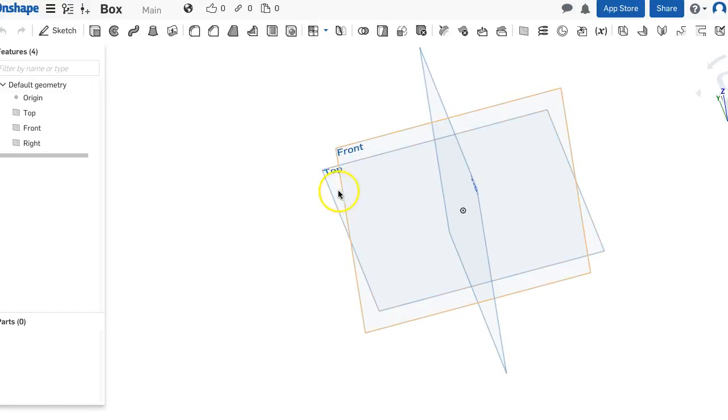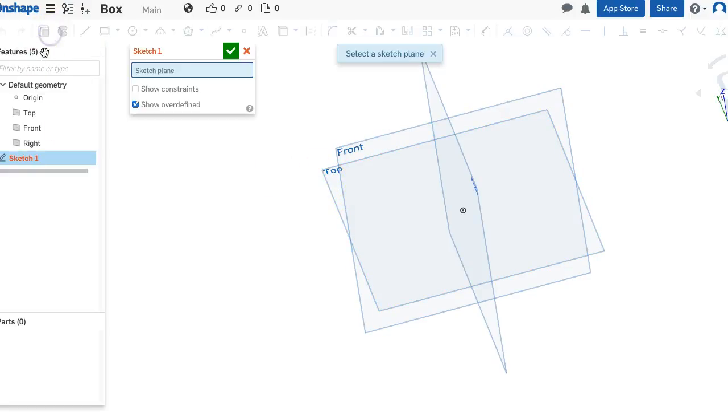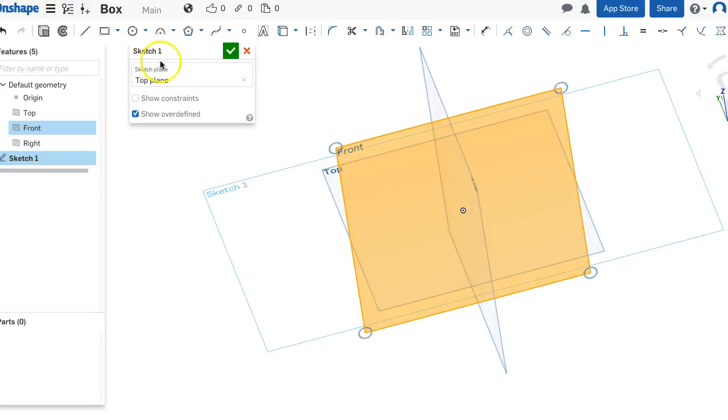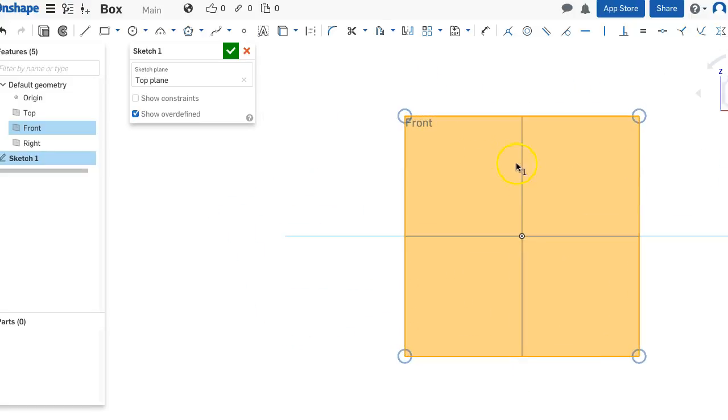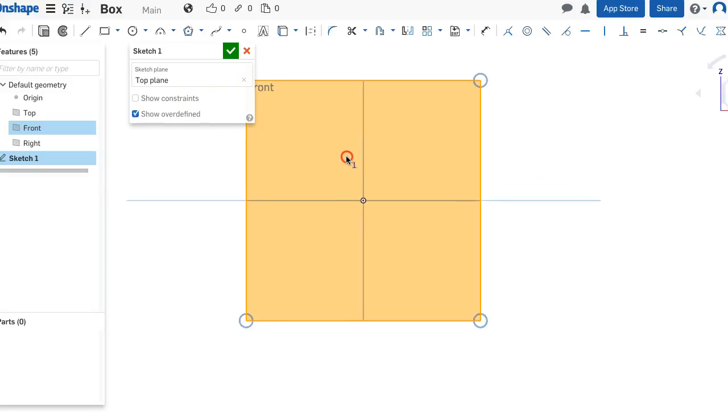What we'll do is create a sketch, and we have to choose a plane. So we'll click the front or top here. I click top, which is fine. Now, as I sketch this, I want to reorient the screen so it's easier for me to see. So I'm going to press the N key, and that's going to bring it up here. I'm going to move it around.